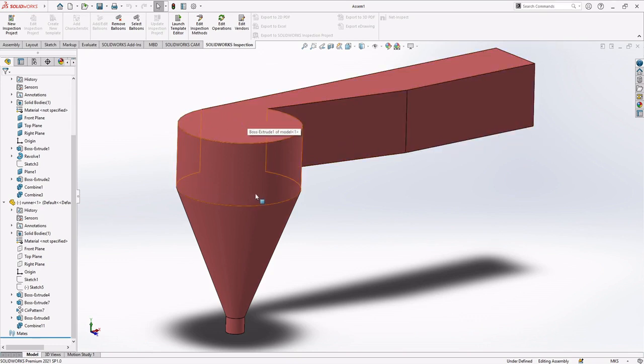So here, in this gravitational vortex power plant, it has an inlet channel where the water is coming in. Over here, we have the conical basins attached to that inlet. The water coming into these basins, inside the basins we have a turbine, and that turbine will extract power from the water and it will rotate. The water will rotate, push the turbines, cause the turbine to rotate, and after that it will exit through the bottom of these basins.